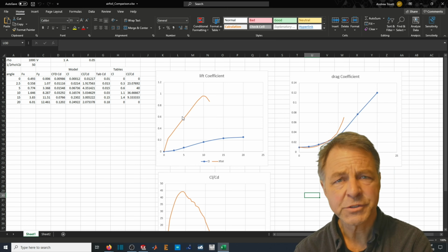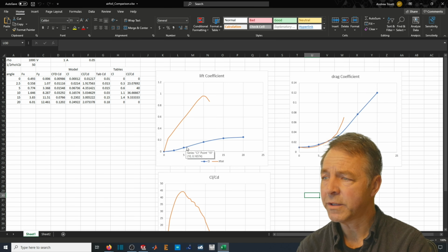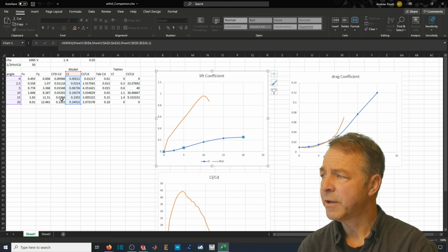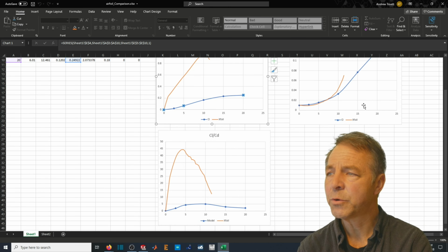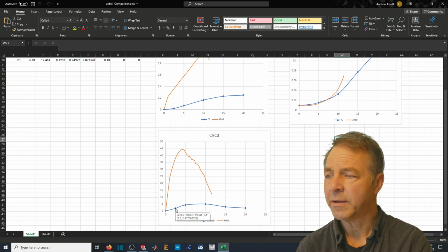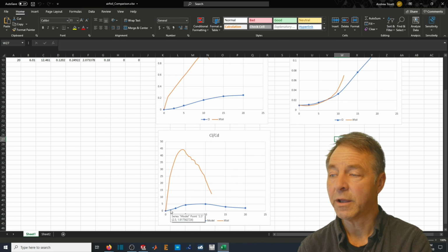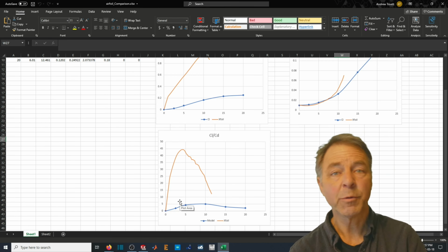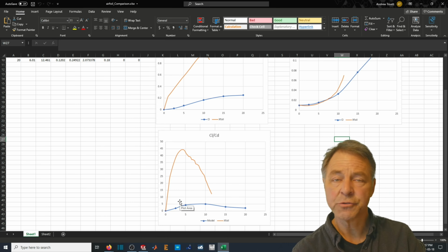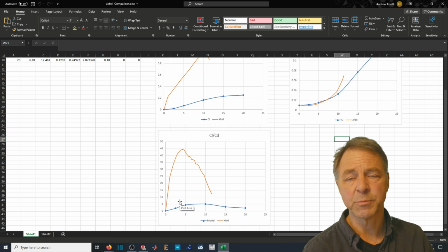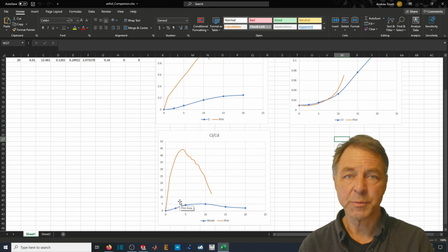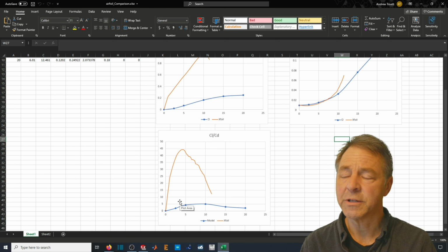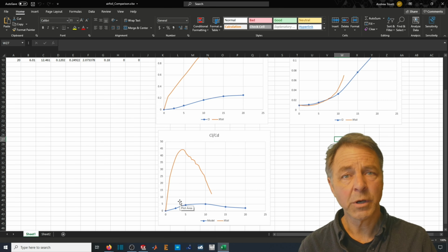The lift coefficient, on the other hand, is totally wonky. Taking the numbers that I used, that lift coefficient is much lower than I should have expected. And so basically my model, after running it, did a reasonable prediction of the skin friction, so the friction drag, which you would expect because that's a simple turbulence model, but the effect of lift, which is caused by the boundary layer and circulation, wasn't very well modeled.